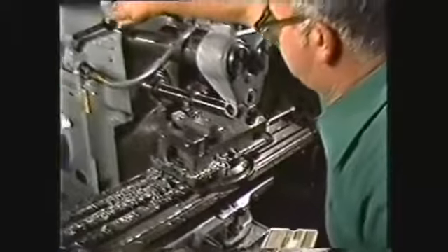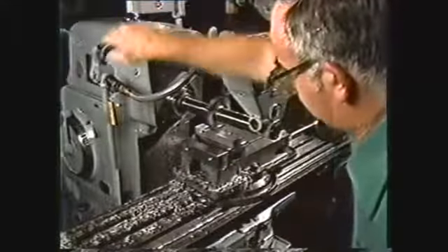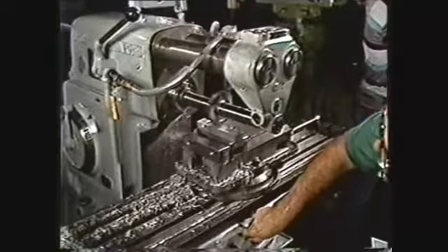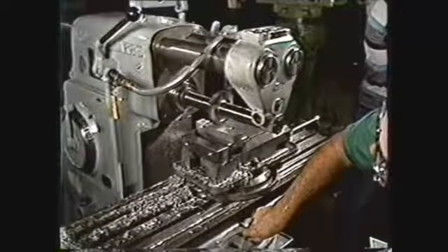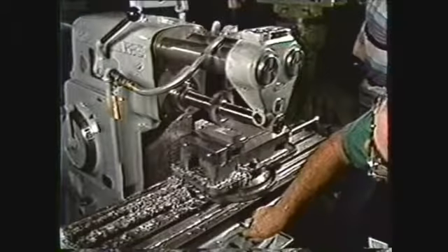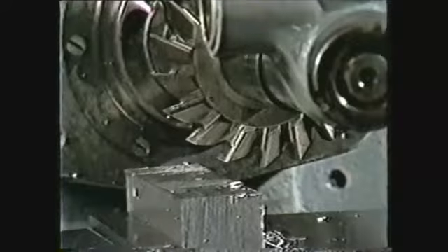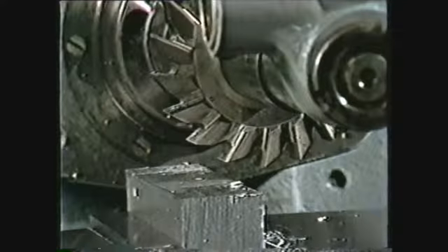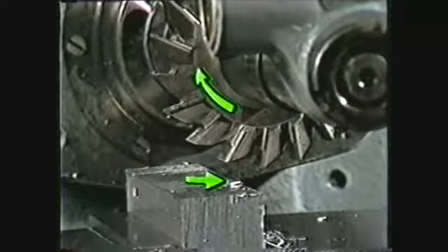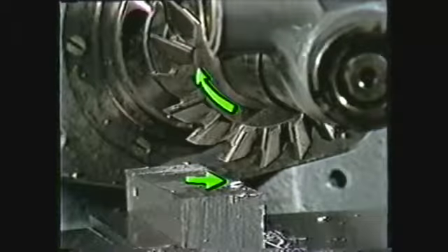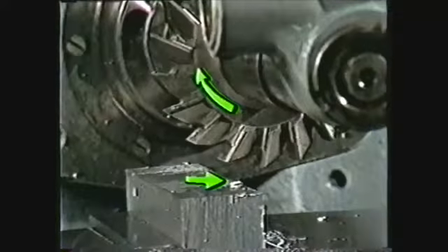It is important to note that on a milling machine, the feed rate is independent of the cutter RPM and must be calculated for a specific cutter RPM. In side milling operations, conventional or up milling is the preferred method. So set up the work to feed into the rotation of the cutter.